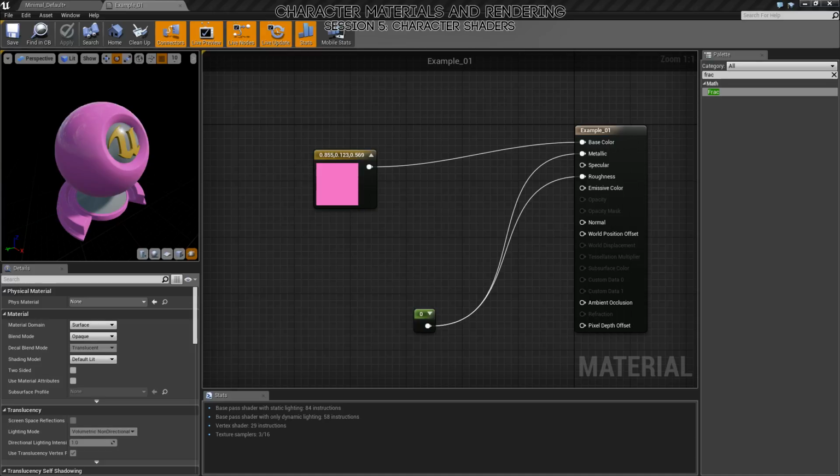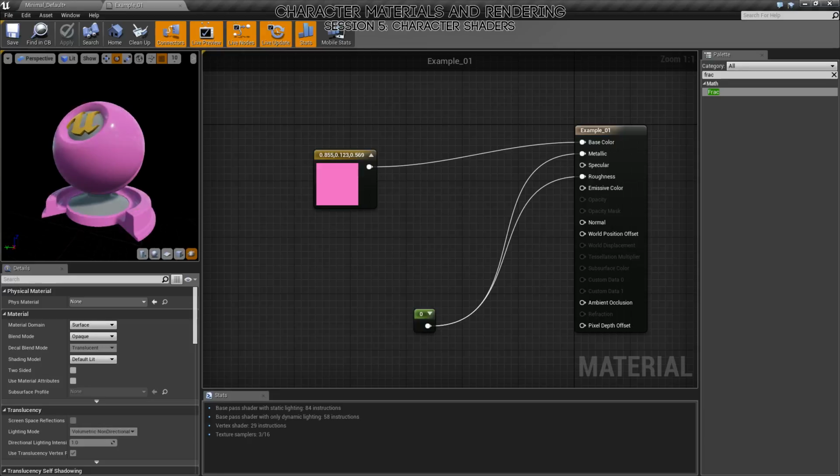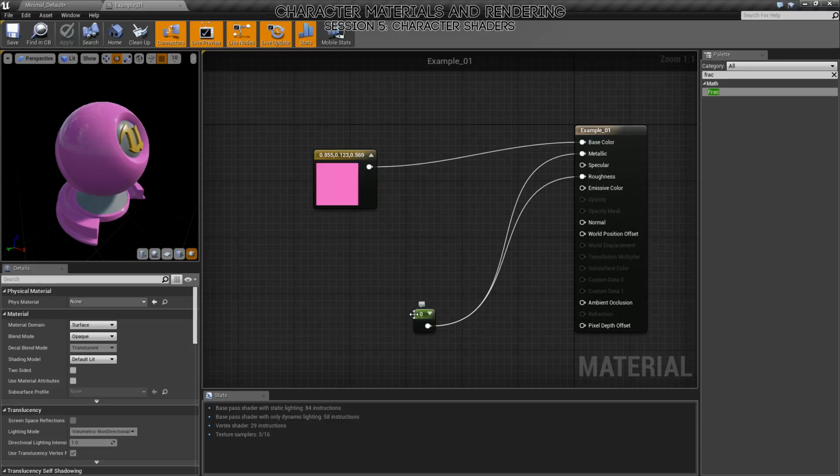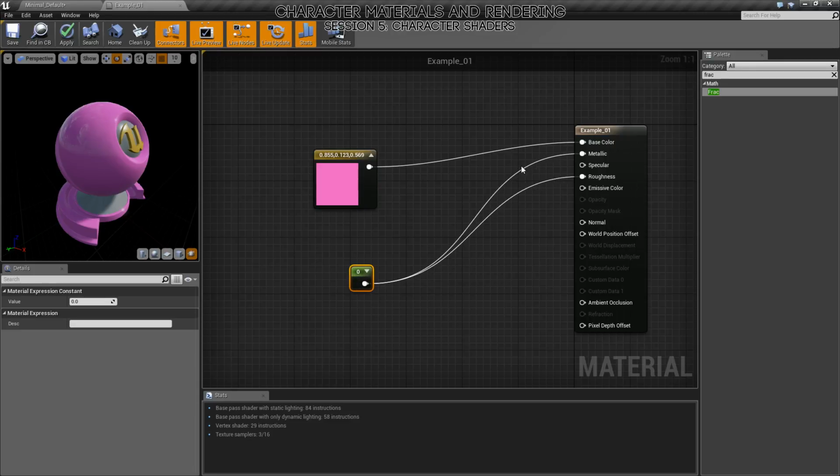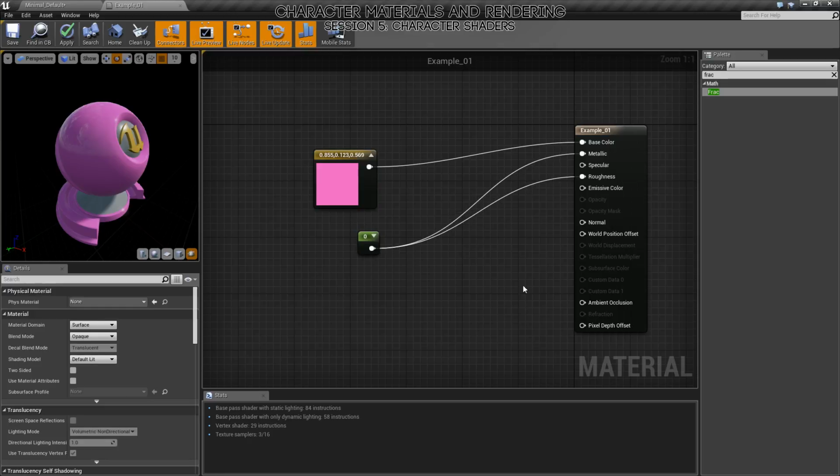Regardless, let's get back to what we were talking about before. So here you can see that we have a very, very basic shader. All it has is a 0 value for metallic and a 0 value for roughness. In terms of what you could expect from a specular shader, this is the equivalent of saying that the specular value is 0.04 and the gloss is 100%.